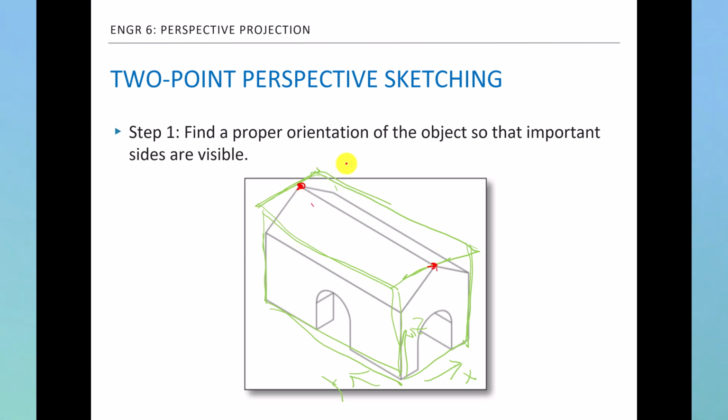So in this case, these points are right at the top surface of the bounding box, and these lines have to be at the bottom, right? And this line has to be at the frontal surface, and so on. Okay, so you have to find the snugly fitting box, the smallest box that contains the object. Then we can measure the width and depth and height of that box, and we want to focus on sketching the box first. Again, don't look at the details of the complex object. We want to construct a minimum box, and we will sketch the minimum box first.